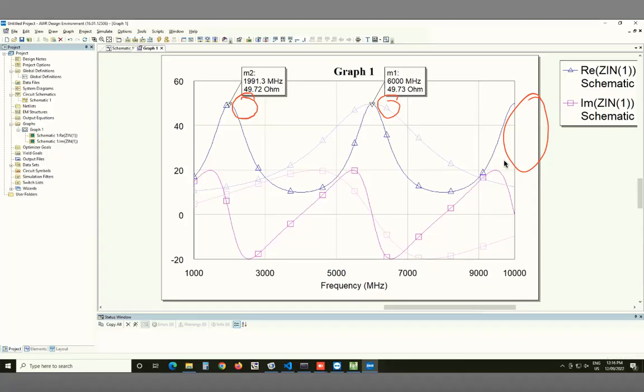And then what about this peak out here? So it is another full wavelength. So this is at this frequency. So again, remember that when I talk about impedance matching, you always talk with respect to the frequency at which we are looking. Initially, we were looking at 6 gigahertz. Earlier, the 90 degree transmission line I made was lambda by 4 at 6 gigahertz. Now I have made something which is 3 lambda by 4 at 6 gigahertz. That's why it's lambda by 4 at 2 gigahertz.